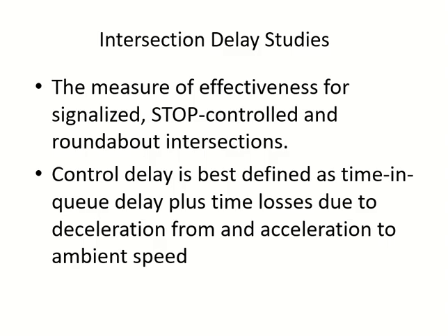So when you are coming close to the intersection, you are going at a high speed normally. As you come closer, you reduce your speed because now you see that you are at an intersection and may have to stop. So this reduction is because of the intersection as well. So that's why we count it in the delay. The delay starts when you have started to reduce your speed.